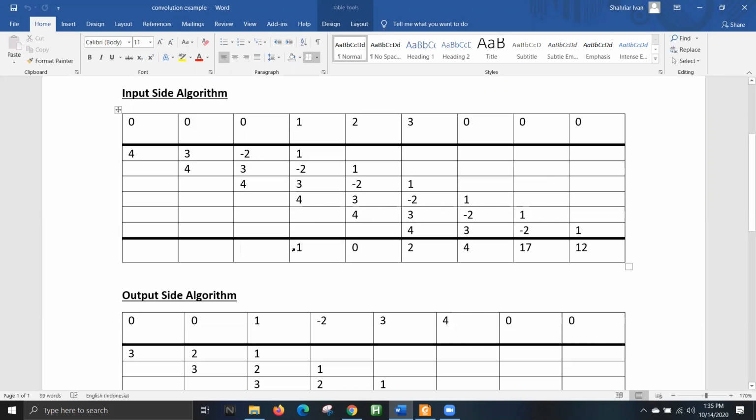So these first two significant values, I'm not talking about the values that do not exist anyway, are obviously coming from incomplete information. But even these two values that are non-zero are also coming from incomplete information. As you can see, they do not match up completely with the impulse response. All three values of the impulse response do not match up with the input signal. But here, this value is coming from all three values of the impulse response, so this value is based on complete information.